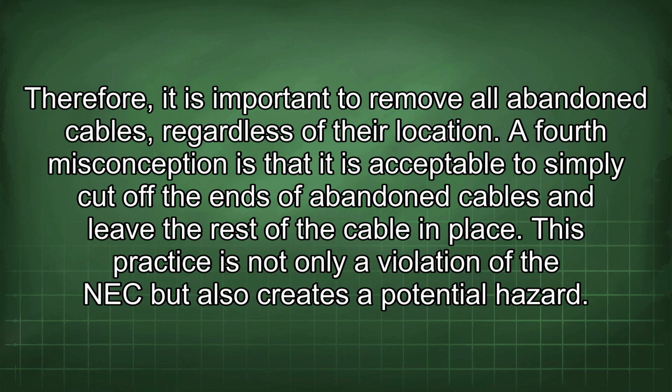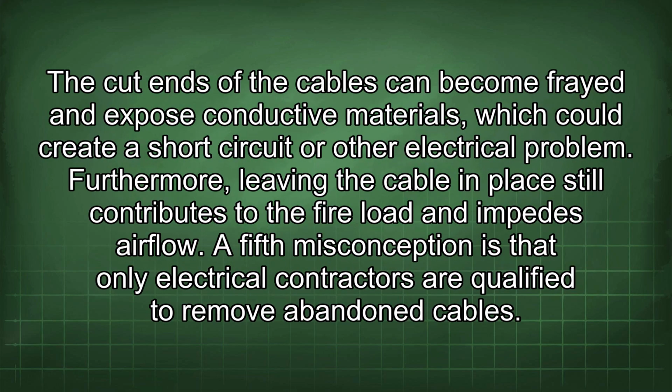A fourth misconception is that it is acceptable to simply cut off the ends of abandoned cables and leave the rest of the cable in place. This practice is not only a violation of the NEC but also creates a potential hazard. The cut ends of the cables can become frayed and expose conductive materials, which could create a short circuit or other electrical problem. Furthermore, leaving the cable in place still contributes to the fire load and impedes airflow.